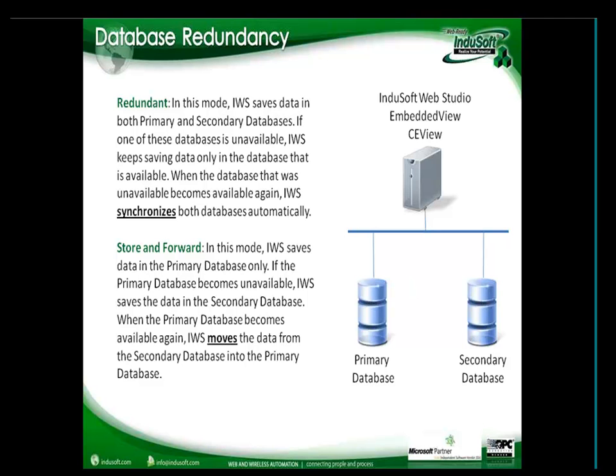If any database, doesn't matter which one, becomes unavailable, InduSoft keeps saving data into the remaining one. And when the other database becomes available again, InduSoft automatically synchronizes the information between both databases and keeps saving data in both. So it's done automatically for you.